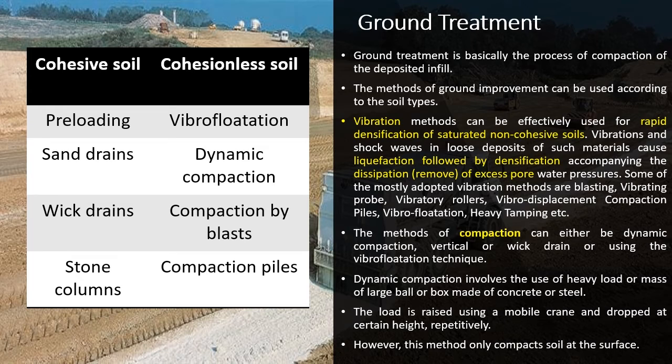Vibration and shock wave in loose deposits of such materials cause liquefaction followed by densification accompanying the dissipation of excess pore water pressure. Some of the most adopted vibration methods are blasting, vibrating probe, vibratory rollers, vibro displacement, compaction piles, vibro flotation, heavy tamping, and many others.